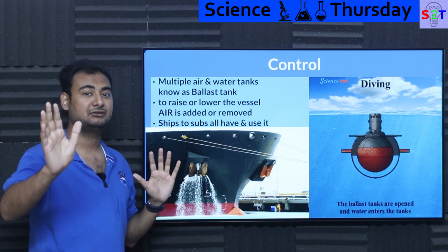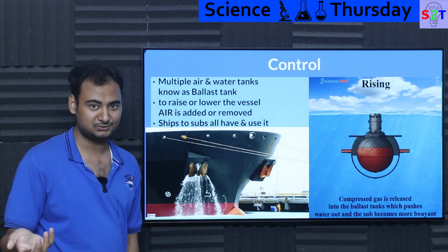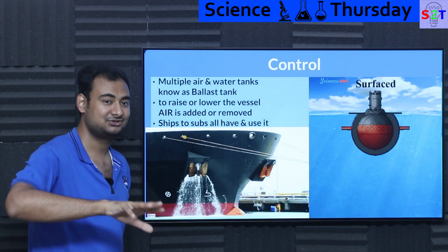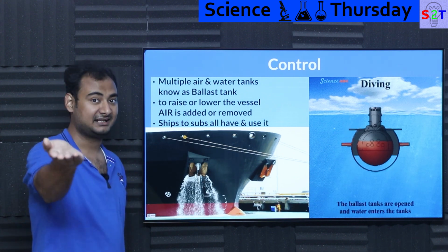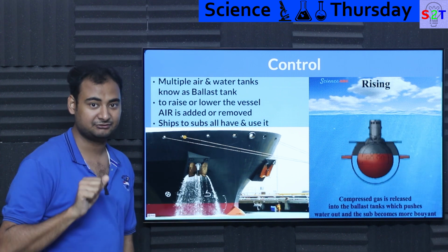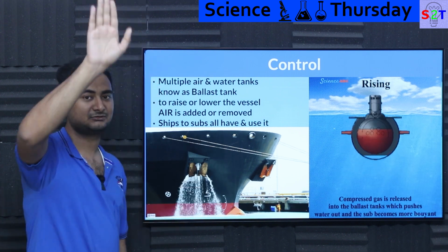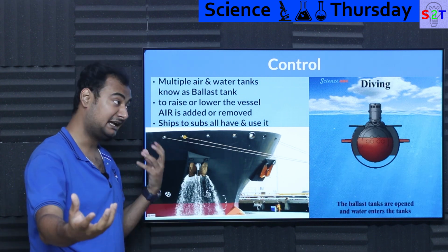And be mindful that trim changes. Let's say you fire torpedoes. They are not few-gram equipment, they are multi-ton equipment. So if you literally fire multiple tons from the front, you have to make sure the ballast tanks are compensated for that. Otherwise you may have a submarine that, if you fire full forward, literally comes out of the water. It has happened. So that's why we have ballast tanks in front and back.